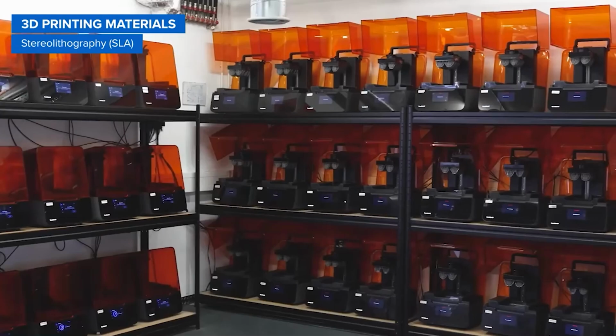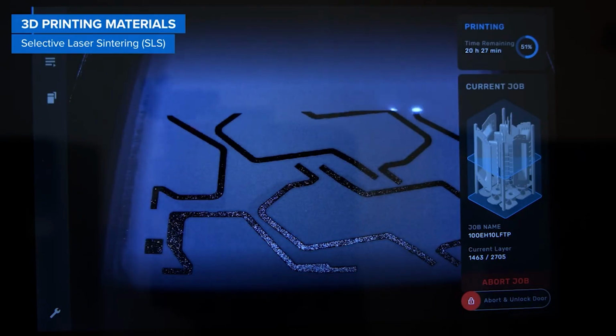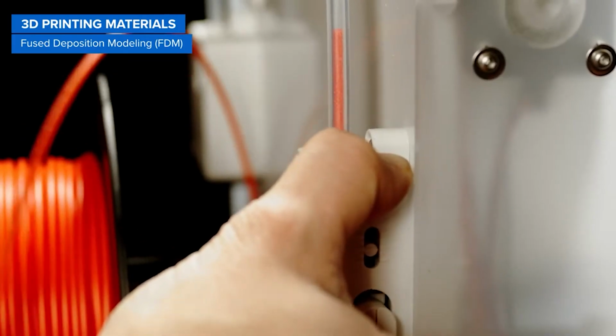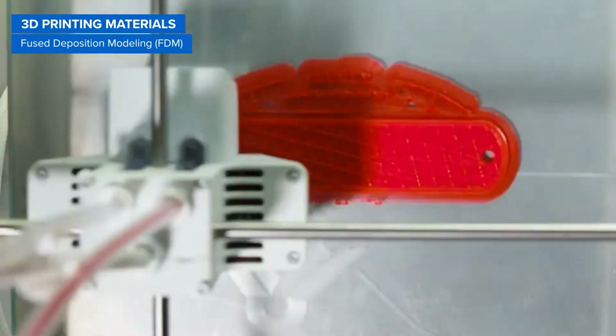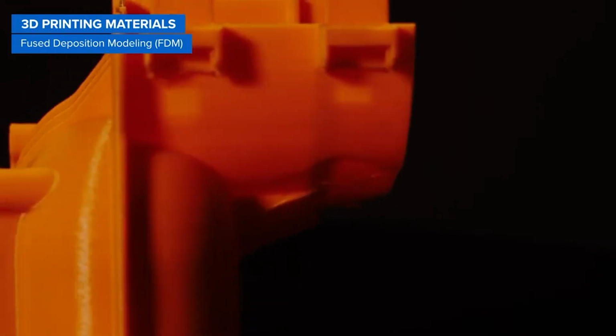Today, several 3D printing technologies are available. Each possesses unique characteristics and fields of application. Among the most popular are SLA, SLS, and FDM. I chose FDM especially due to its cost-effectiveness and ease of use. Fused deposition modeling operates by extruding melted thermoplastic filament layer by layer to build up a three-dimensional object.